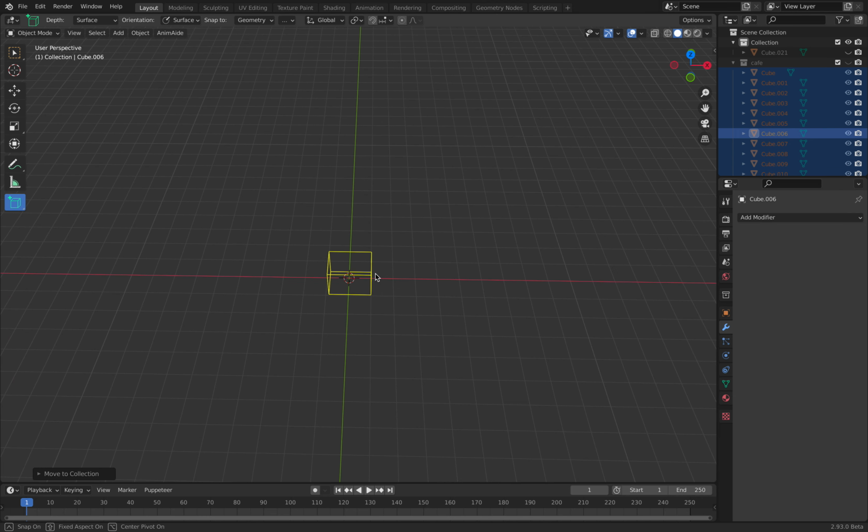This guy, if you want to cut in, I just select all these three, 1, 2, 3, holding Shift, Command J, push this a little bit in and make a cut into this guy. Control-Shift-B. So we have something that goes in. So this body is too big. So the robot looks menacing.